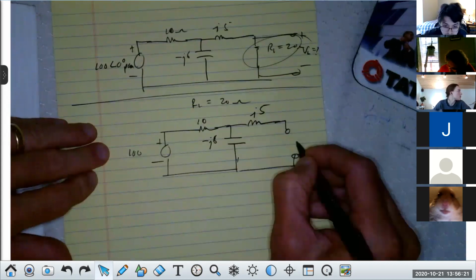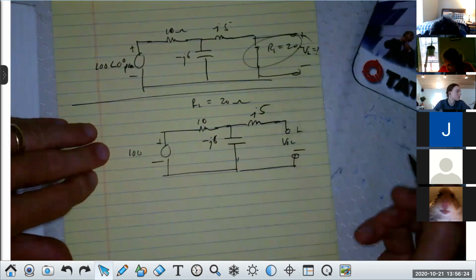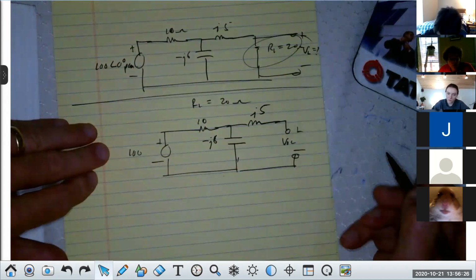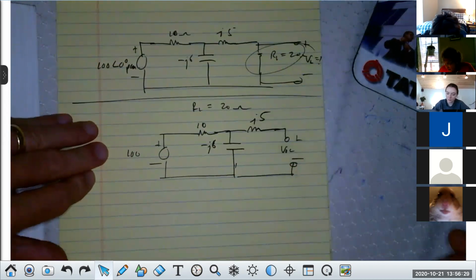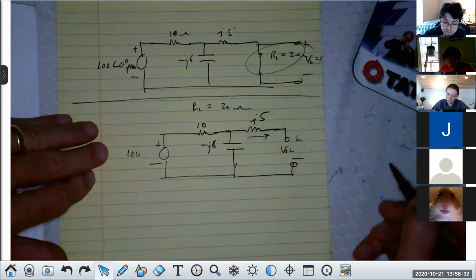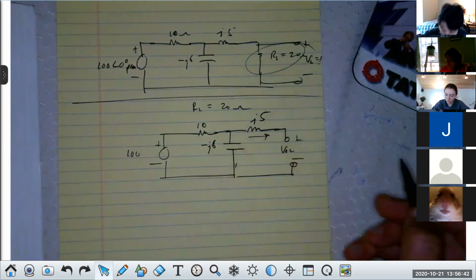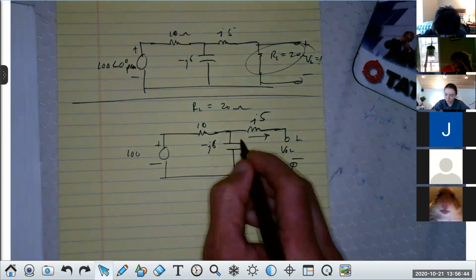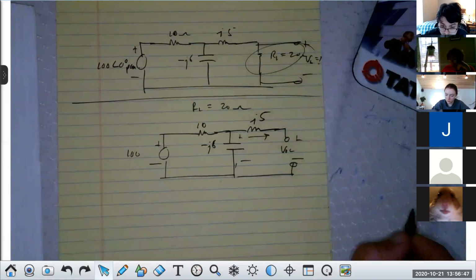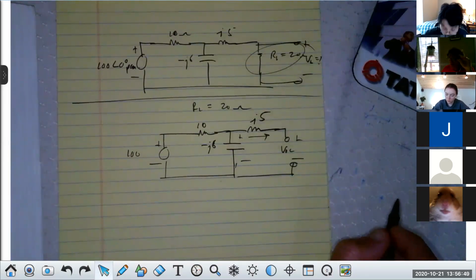Now this is plus to minus V open circuit, right? Can y'all see this? How much current flows through that J5? Zero. How much voltage is across J5? Zero. No current across the J5, no voltage across it. Therefore, the voltage across this capacitor, I put the plus minus, is VOC. Do you agree with that? Yes. Now, I gave you a quiz that asked fundamentally that, and a lot of people got it wrong because